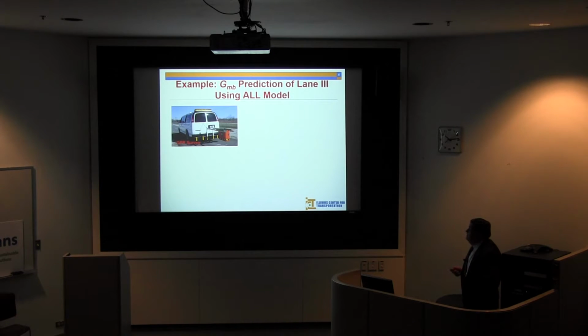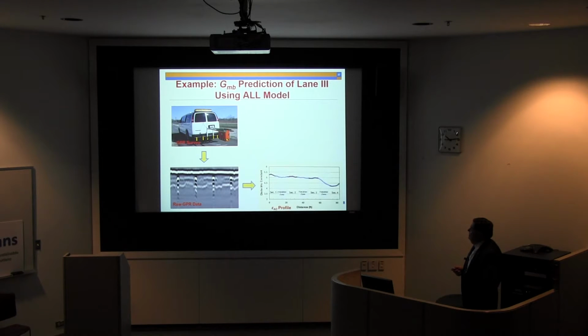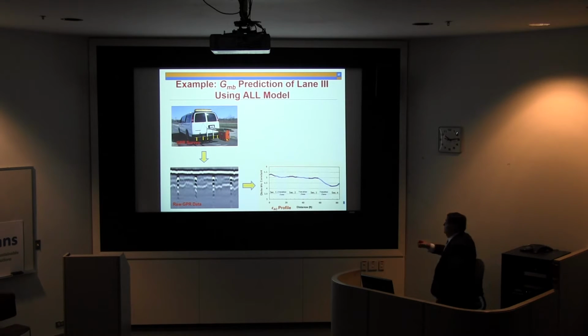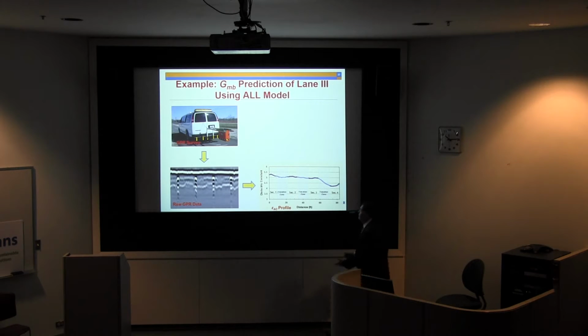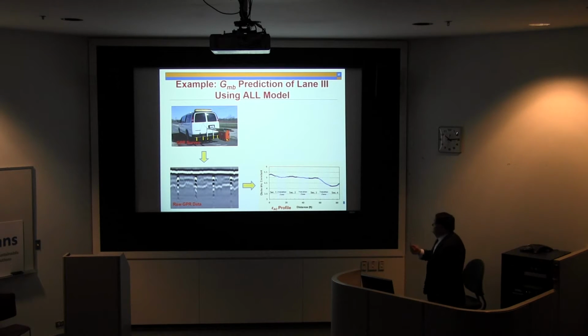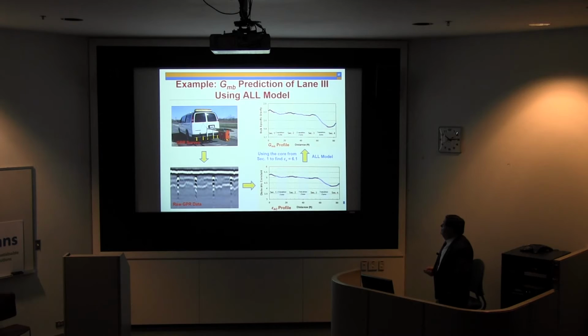This is the GPR survey. We find where the copper plates are, we take this data, we analyze it, we find what's the dielectric constant for all the different sections. Of course, these are transition zones because you cannot kind of stop and have different thicknesses. So you have to have a transition during the paving process, okay? So it's more construction related. So you get the dielectric constant. In this case, we found that the dielectric constant for the stone is 6.1. We put this in the model, and we get now the bulk specific gravity, which tells me what's the density that I have for each section.